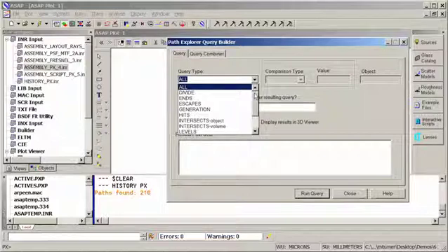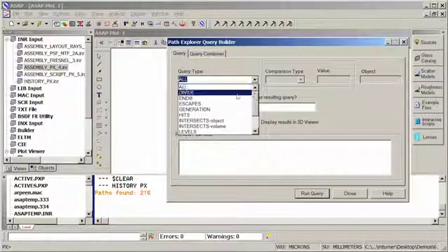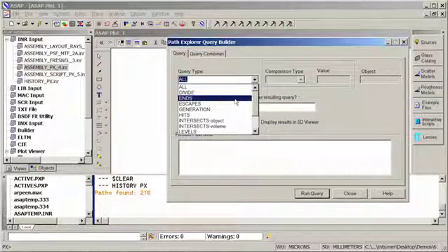What queries allow us to do are isolate particular subsets of those 216 rays. For instance, I can go through and look for those rays that divide at a particular surface or object within ASAP. Similarly, I can look for rays that end on particular objects, or rays that escape the system. These would be rays that did not end on an absorbing surface. I can sort the rays by their generation. The 0th generation are the first rays that come from the original source, and then each level of splitting and/or scattering will create a subsequent generation.